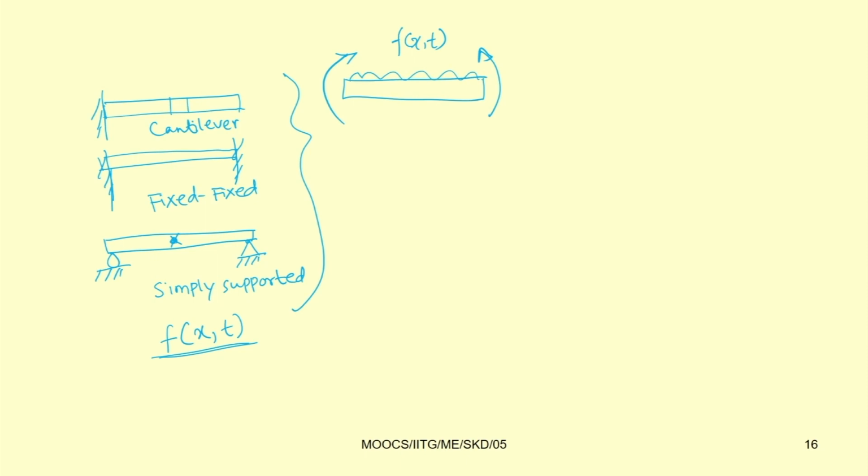As it is subjected to pure bending, we can write M on this side, and on the other side it will be M plus ∂M/∂x times dx, and also the shear force. Let the shear force on this side equal F. On the other side it will act in this direction and be equal to F plus ∂F/∂x times dx. So, this is the force acting on the right side.